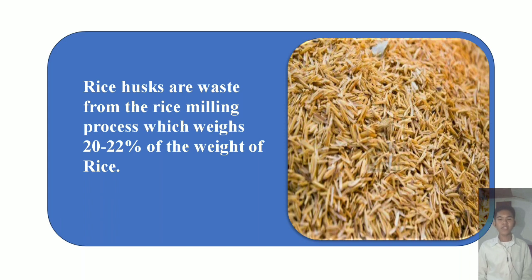However, the use of rice husk was still not optimal. This is due to the characteristics of the rice husk, which are coarse, have low nutritional value, have a low density, and have high enough ash content. Additionally, rice husk as the biomass in the porous concrete can affect the strength and hardening of the porous concrete.